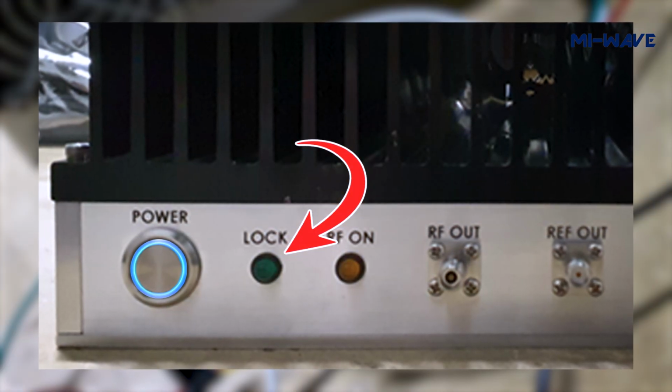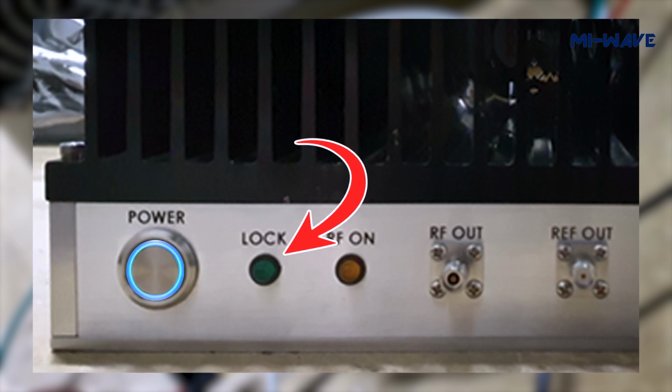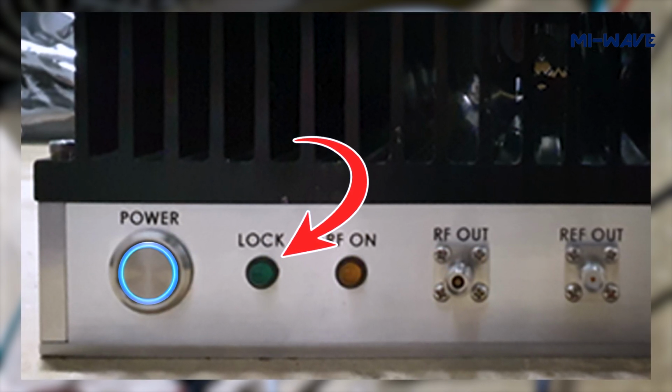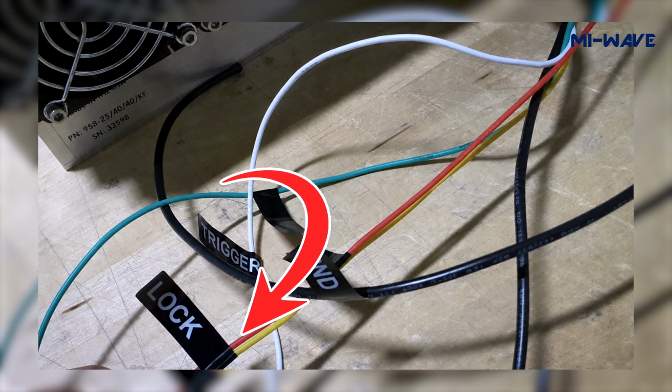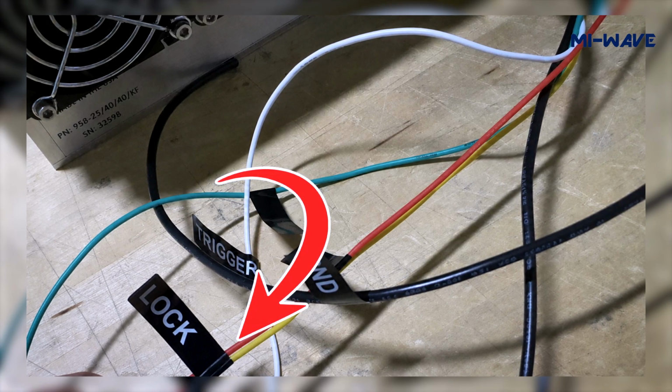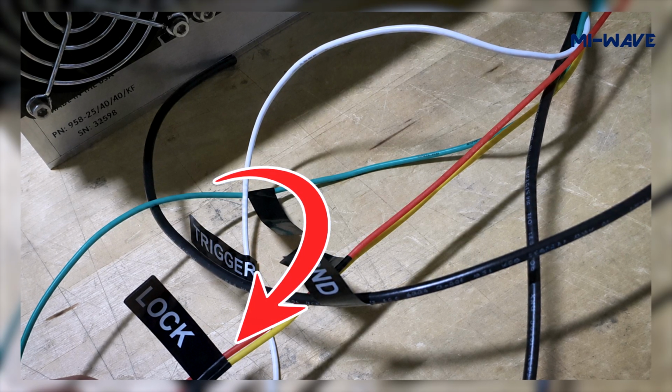When the synthesizer is successfully locked to the external 10 MHz reference, the lock indicator will illuminate. In applications where the synthesizer is installed inside an enclosure and the LED indicators are not visible, the lock signal can be used to verify that the external reference signal is present and the synthesizer has achieved a valid reference lock condition.